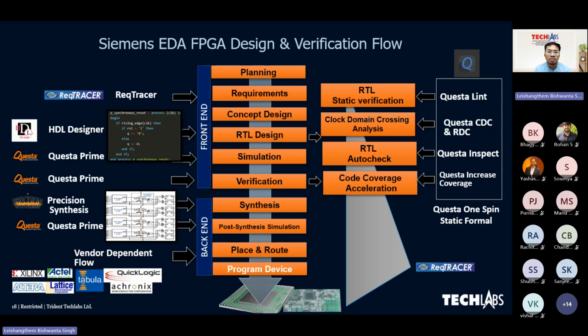So this tool can perform your simulation verification at RTL level as well as netlist level. But for DO-254, we are performing simulation and verification. The elementary analysis of code coverage is very important. And sometimes you cannot achieve 100% code coverage because there is always a coverage gap involved in your design.